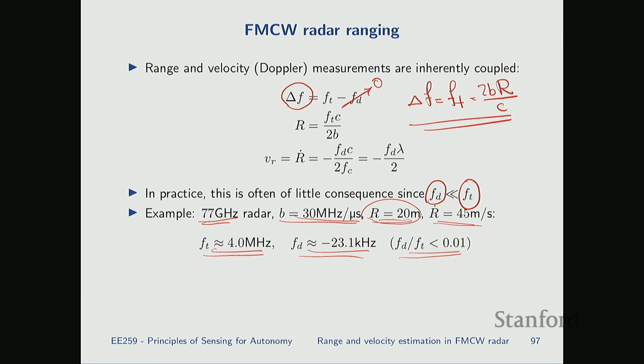Now back to the question: when we were talking about CTFM, we didn't even mention Doppler shift, right? The reason is the situation in sonar is even simpler than this. Even in the case of radar, when you look at the frequency of the IF signal, you can ignore Doppler because it's so small compared to the frequency shift you get from the range.